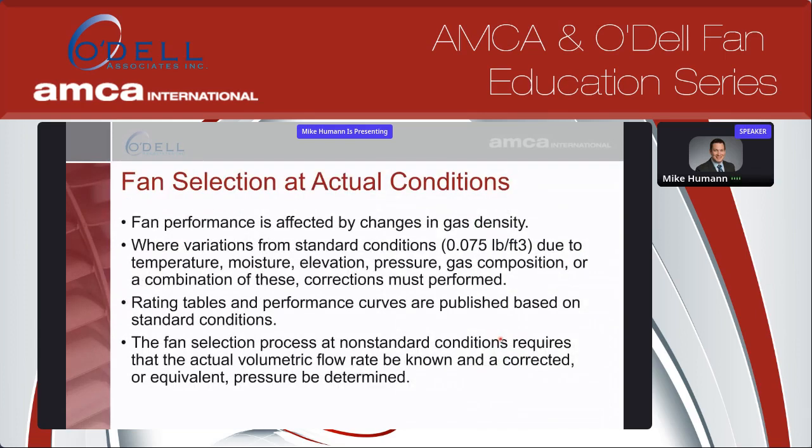So a couple of notes when you're talking about fan selection to actual conditions: we have to remember that performance is affected by any changes in gas density. If there are any changes in temperature, moisture, elevation, or other factors, corrections must be performed. All rating tables from fan manufacturers are published based on standard conditions. So that's where fan selection really helps you, because the fan selection process can take that non-standard condition into account versus what you see in a bulletin or off of a cut sheet.